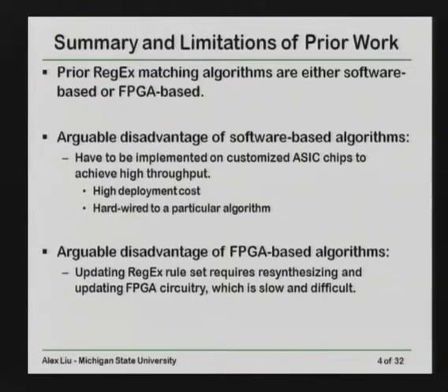Using ASIC chips incurs high deployment cost, and they are hardwired to a particular algorithm. If you later change your algorithm, you have to throw the system away, burn new ASIC chips, and design new systems. Another category of regular expression matching algorithms is FPGA-based.